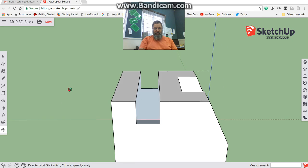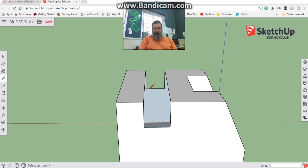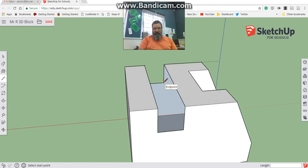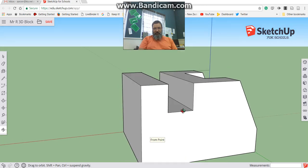I need to close up the bottom of this channel. So if I go back to my pencil tool and I draw a line from the bottom of that point there, there's the bottom of this line, to the bottom of this line on this side. So I've drawn that line across and it's closed up that face. If I do the same on the other side, from that point there to that point there, it closes up the rest of it, and now my block is solid again. I can no longer see inside it.